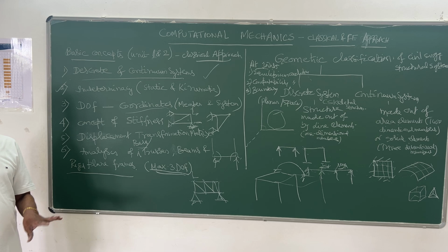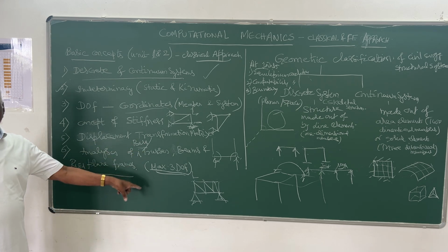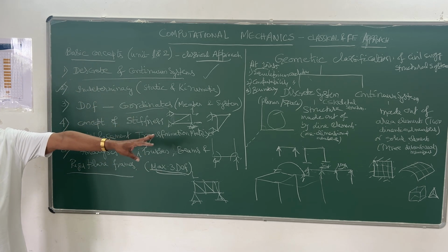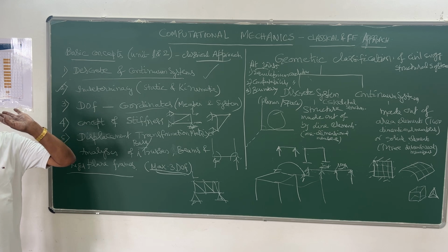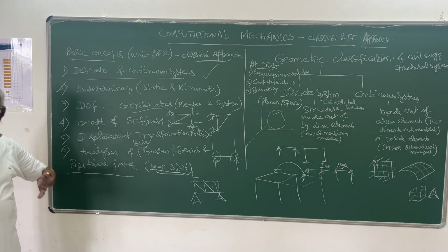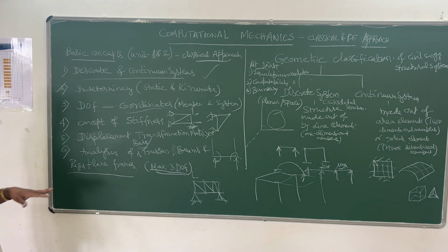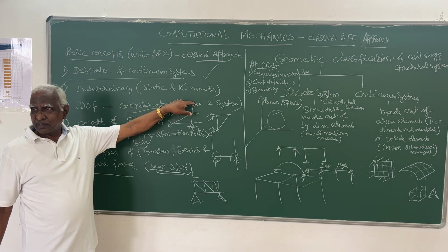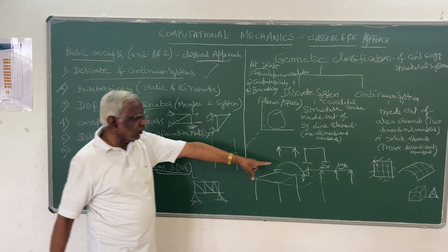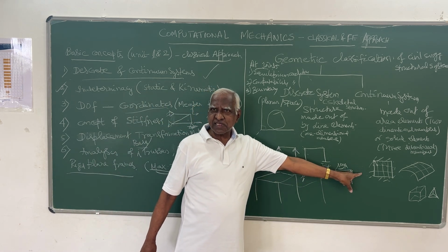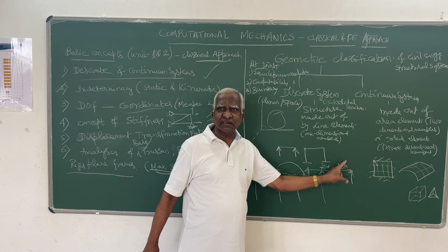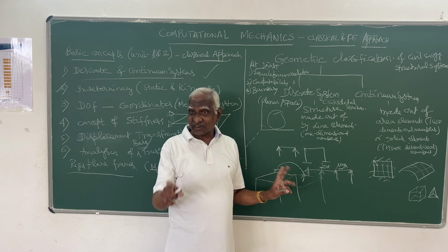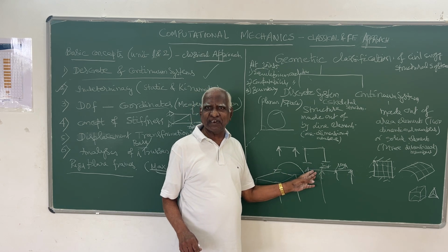In addition to this, we have to determine the displacements at all these joints or nodes. Right? So the number of unknown displacements at each joint is called kinematic indeterminacy. Number of unknown displacements, which I told here. Number of unknown displacements is only rotations, 3. That is kinematic indeterminacy. That is degrees of freedom.